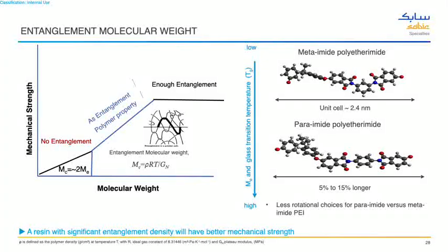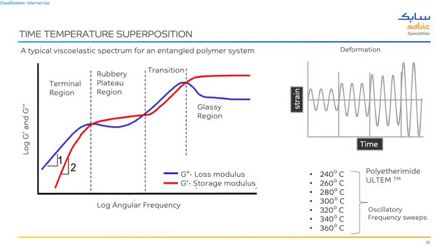What I'm trying to say is that these rheological tools connect the process, structure, and property to product performance. I have a couple of other things to show. I'm touching back on the rheological tools again. How do you connect time-temperature superposition? For example, here you take a polyetherimide resin. I take measurements at six or seven temperatures, and I can create a master curve like this.